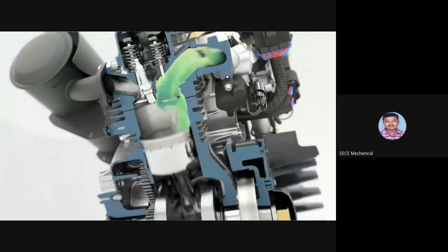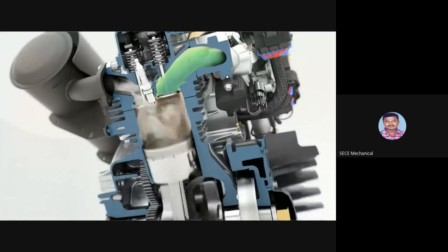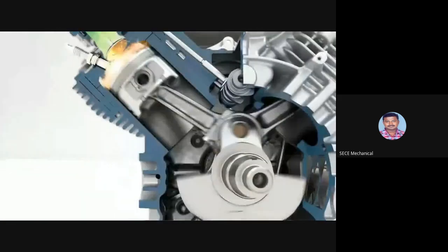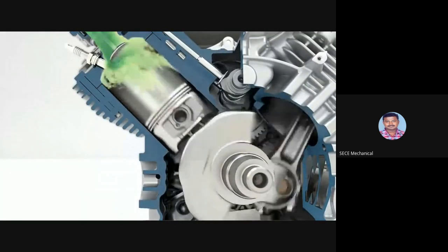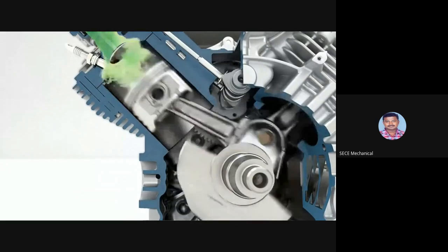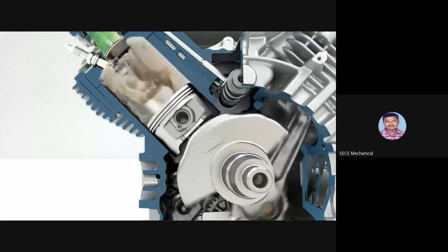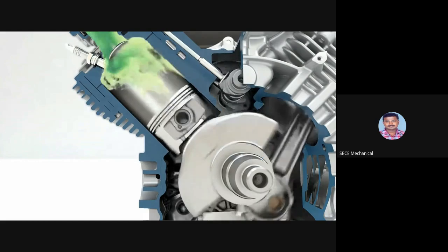often control more than just fuel delivery. The spark events are also controlled by the ECM. Depending upon engine speed and engine load, the spark event may be required to occur much sooner or later in relation to the piston traveling toward top dead center. Variable spark advance is a tool used to always keep the engine producing maximum leverage on the connecting rod and crankshaft, thus making the most torque and efficiency possible.